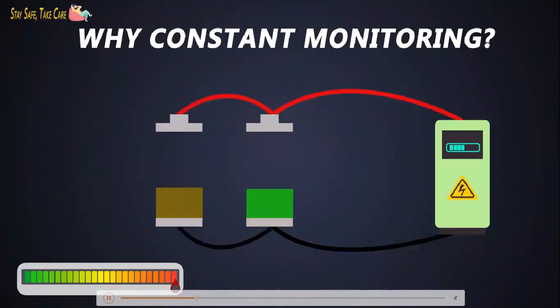There are always slight differences in the state of charge, the charge rate, capacity and impedance between two cells, even if the cells are from the same manufacturer and produced in the same lot. While charging or discharging these cells altogether, some cells experience a lot of stress in the battery pack, so they lead to degradation.